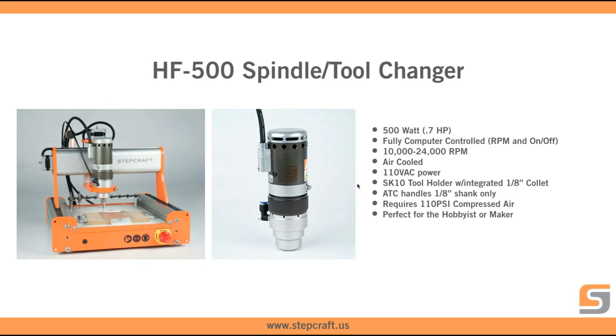So this particular spindle is great for hobbyists, for makers. I have jewelers that use them. Basically, anybody that would not need a ton of power. Believe it or not, this spindle with 1/8" tools, it'll cut aluminum all day long. You're not going to take 1/4" passes, but 15 to 20 thousandths passes, it's going to be fine. It's a very precise spindle. It's just not super big, but it works great.